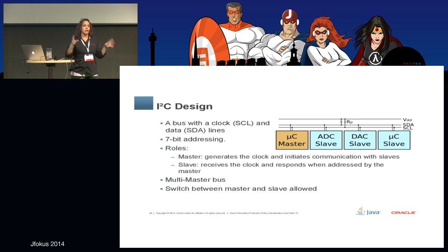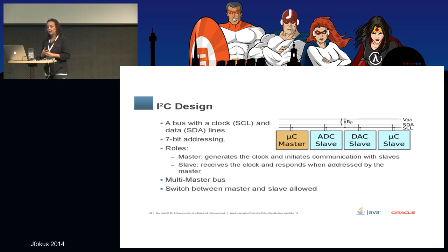You can connect multiple sensors on it as long as they have different addresses. You normally require a pull-up resistor to connect any I2C. The good thing is the Raspberry Pi already has an internal pull-up resistor, so it's a direct connection, and you don't need that external resistor anymore.